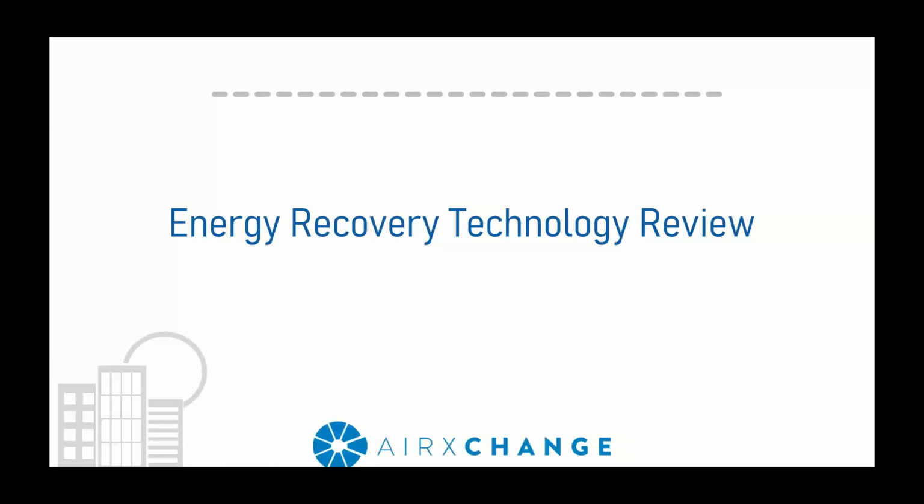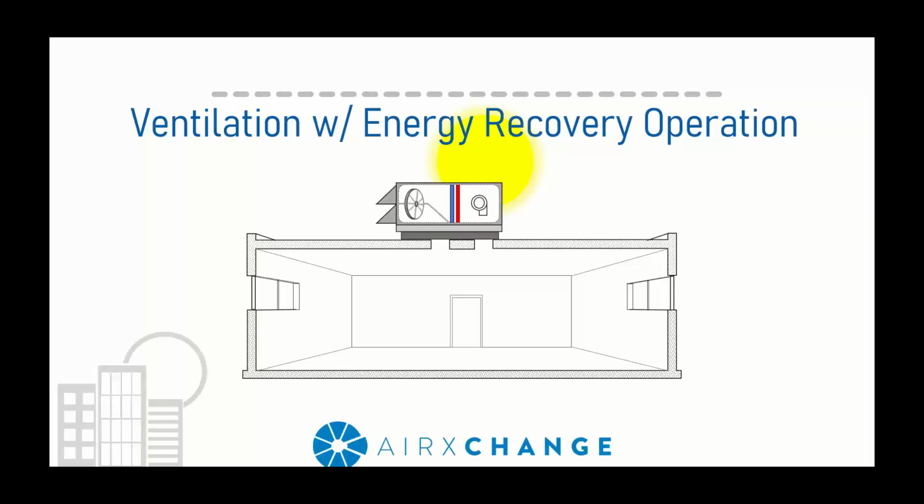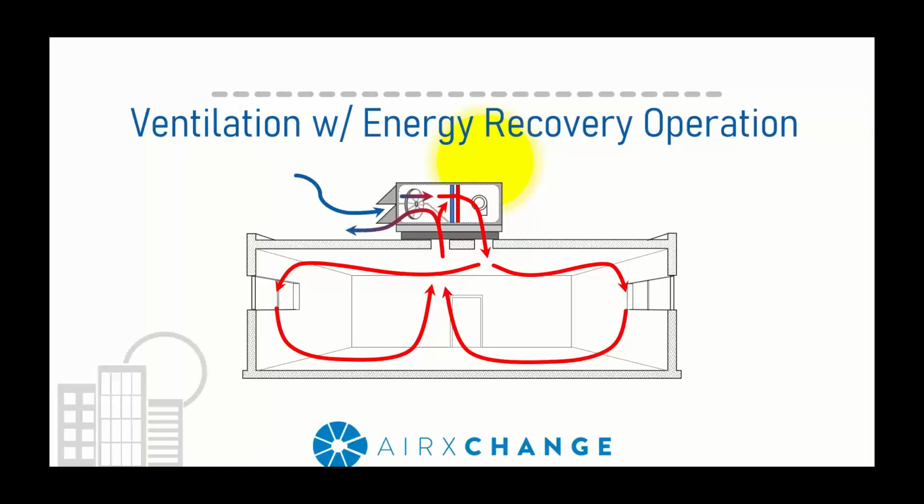Okay, so really quickly, I'm not going to go too deep into this, but I'm going to talk about the basics of energy recovery operation. So you may remember this slide from earlier in our conversation. We're just taking the same process and adding an energy recovery system or energy recovery component into the system. I often refer to energy recovery as a load shift, where you're essentially shifting the ventilation load from the heating and cooling element over to the energy recovery component that's using the low grade thermal energy that's just normally exhausted outside the building.